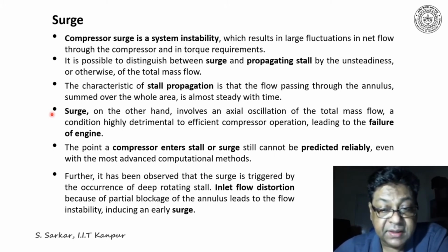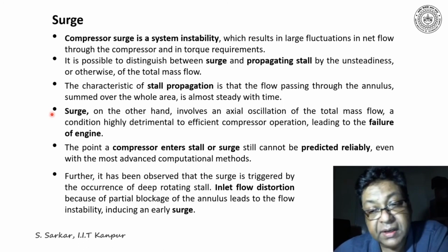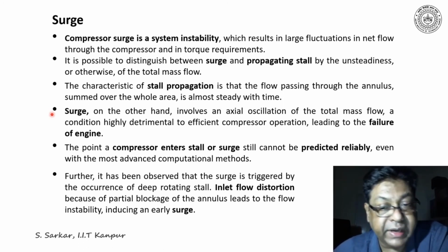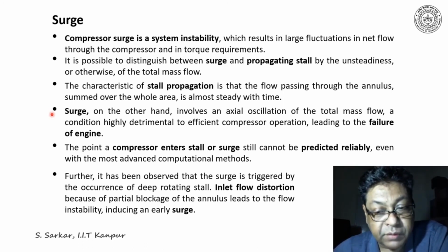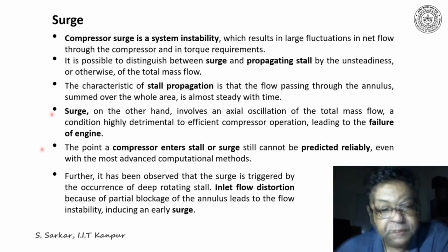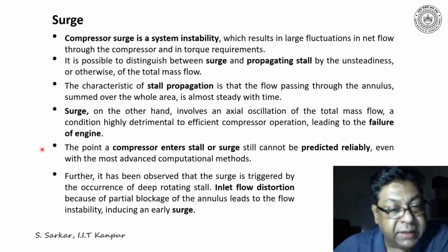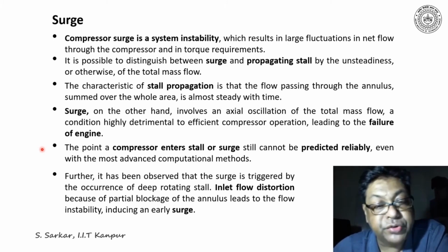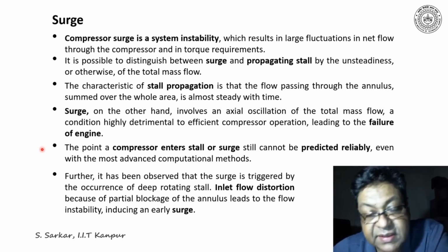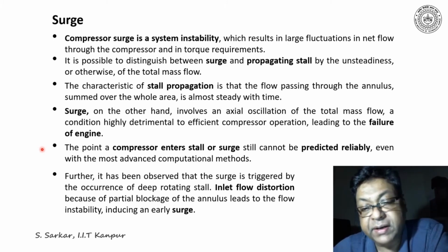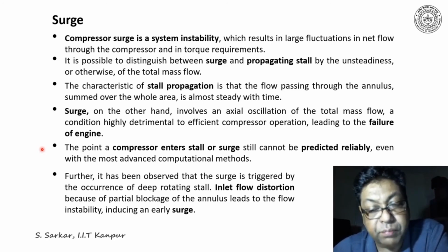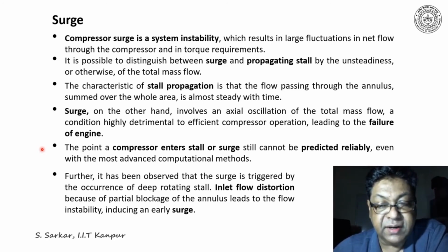The surge is very dangerous, which may lead to the failure of the engine because of flow oscillations. It should be noted that the point at which a compressor enters stall or surge still cannot be predicted reliably even with the most advanced computational methods.